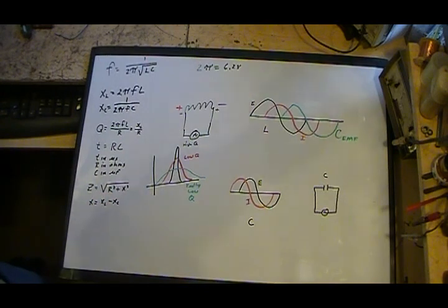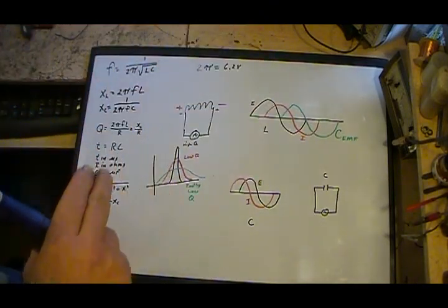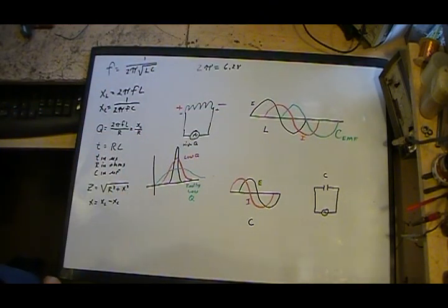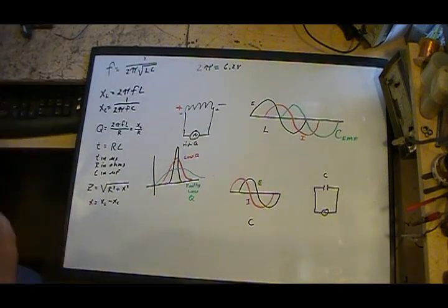The whole purpose of that RC filter is so that the AVC can still work as far as a weak signal versus a strong signal, or a signal that is slowly fading in and out, trying to keep the volume on the same level, but is not affected very much by the normal changes in tone and level of the audio signal when you're listening to music or whatever.